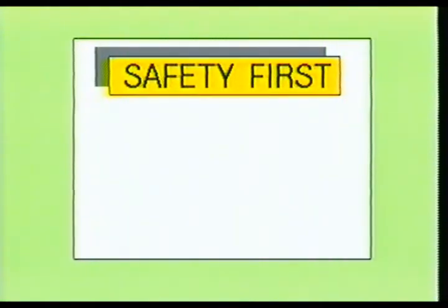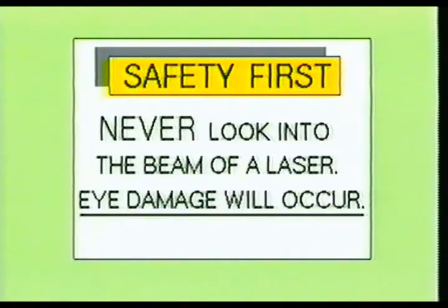Before proceeding into the subject of laser theory, you must first be knowledgeable of the safety precautions which are to be used when operating or working on any type of laser device. First, never look into a laser device when the power is turned on. Even at very low power outputs, the laser will cause damage to your eyes.